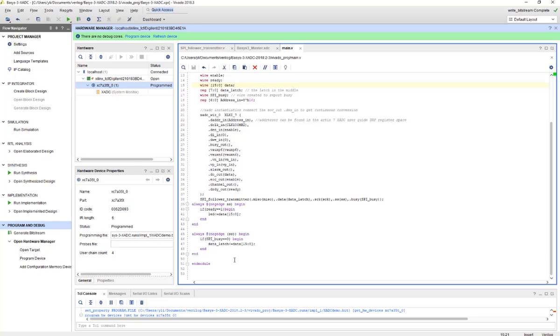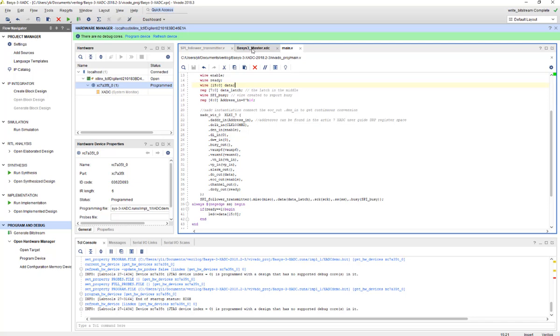I don't know where that potential problem will be, but it sounds like it doesn't like the design when you input a clock to a GPIO pin for some reason. There are some dedicated clock pins on the FPGA that I can use to input a clock into the FPGA, and I didn't find these pins. So Vivado, from the report, gives you a solution to it, and I used it, and that worked.